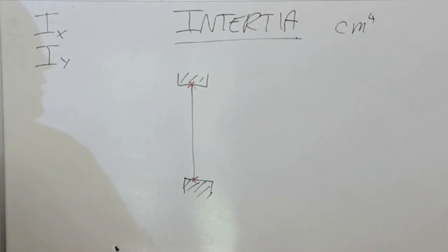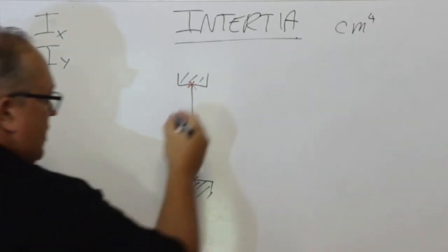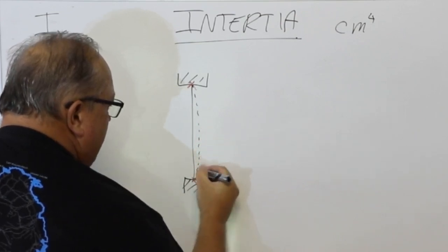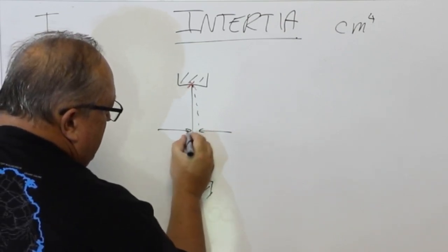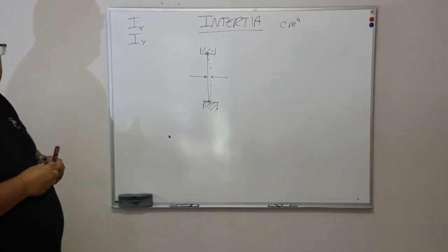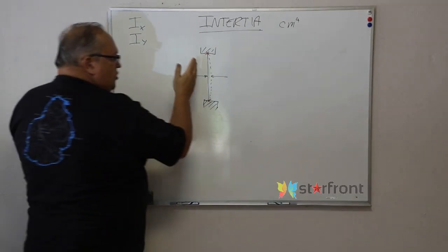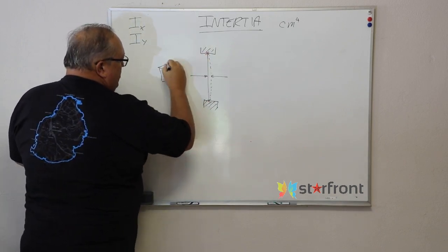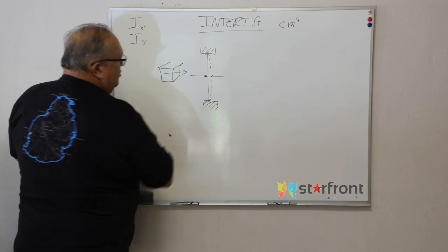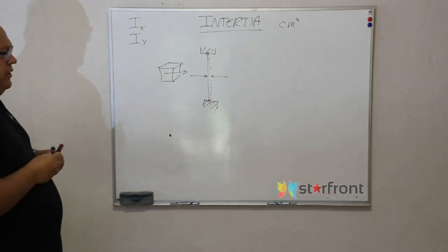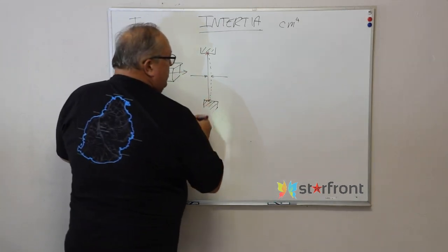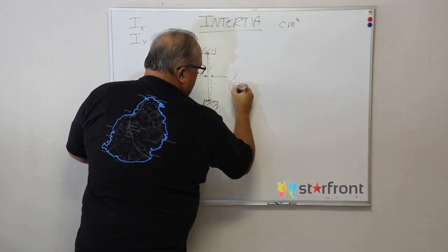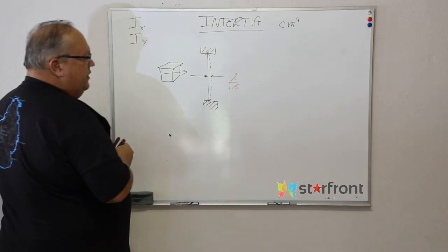And the national building regulations limit the maximum amount that this aluminium profile may deflect from its normal position. And the force which is causing the deflection of this profile is that parcel of wind which is impacting against my window. As mentioned in the wind load lecture, this maximum deflection is the length of the profile divided by 175.